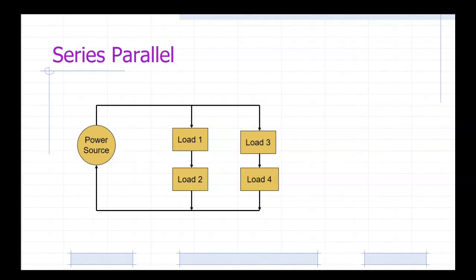Series parallel. The great thing about series parallel is it kind of gets rid of some of the weaknesses. If one load goes down, the whole thing doesn't go down. You might just lose these two right here. In parallel, the bad thing about it is that if you short a load, everything else has to pick up.